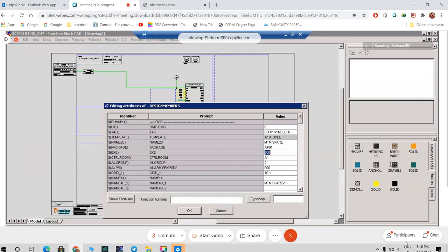And arming function, I think it will come in this protection sphere. Suppose like main steam protection, there is an arming function. Suppose once your main steam temperature crosses beyond a particular point, then only that protection is armed. So that is activated after that. After that, if your main steam temperature comes down, then it may cause a trip. Otherwise, the function will not be activated. So this arming function is basically for that.